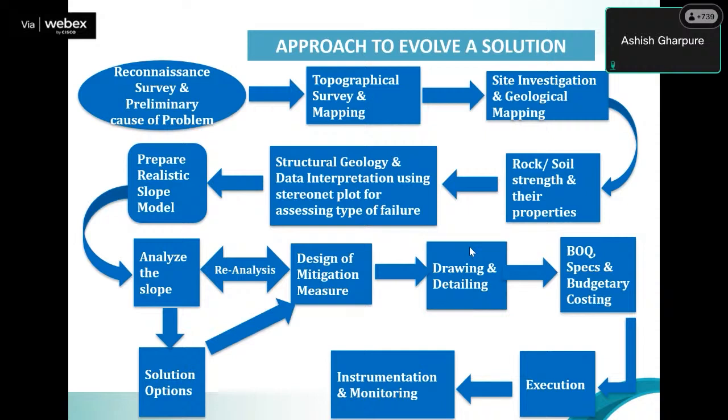The step-by-step or the scientific way to get to a solution is this: have a reconnaissance survey, where preliminary causes of the problem can be identified at site. Do topographical survey and mapping, then plan a site investigation for geological mapping, so that you get rock strata details, and geotechnical as well. So soil strength and their properties. For rock, the structural geology, data interpretation, stereonet plots, and for soil, usually lab investigation as well as field investigation through boreholes.